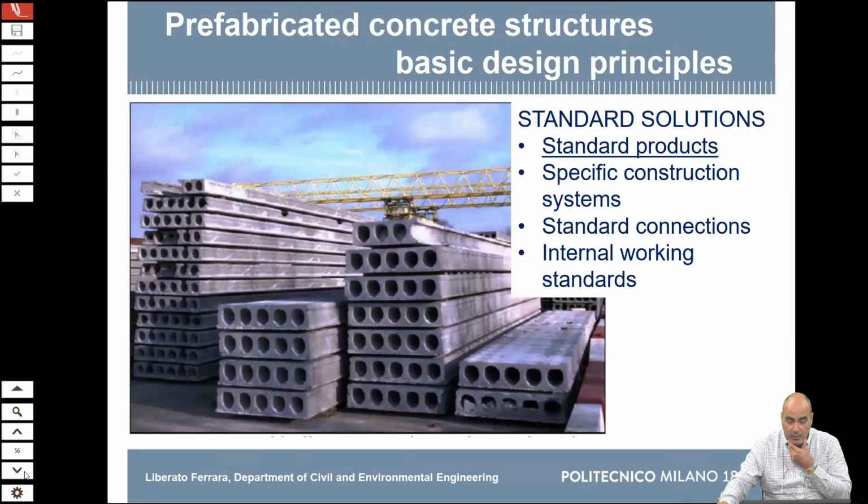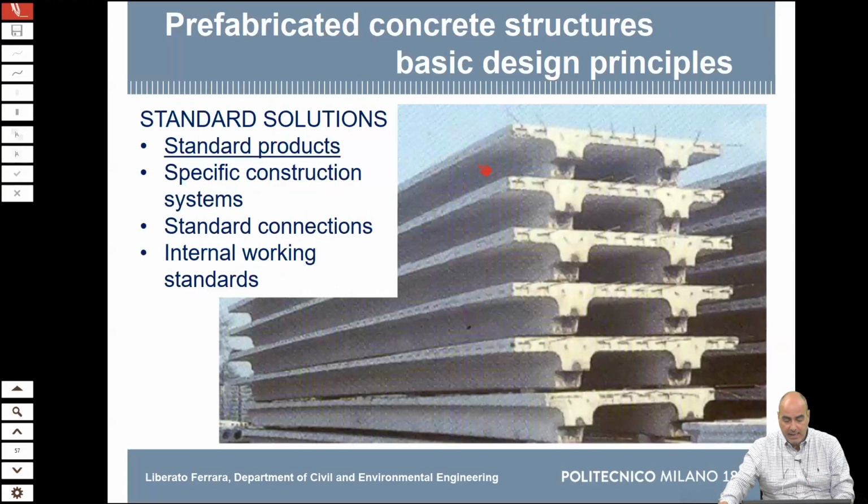And there are a few more slides on when we spoke about standardization. For example, hollow core slabs come in a limited number of sizes. The width is generally fixed, 1.2 or 2.4 meters, because it's the width of the precast runway. But they come in a fixed number of depths with shapes. So you can really limit the number and go into standardized construction.